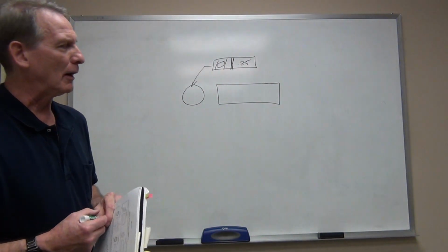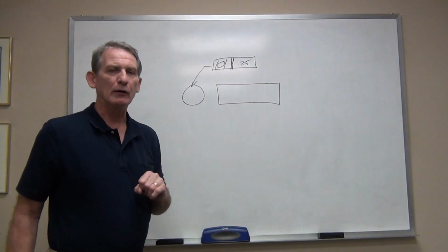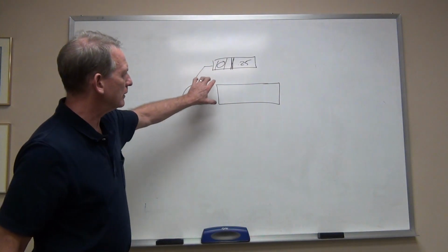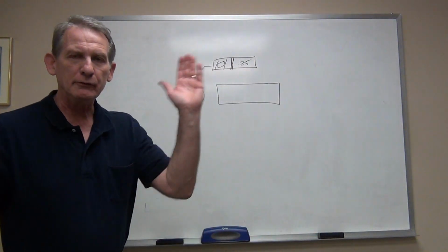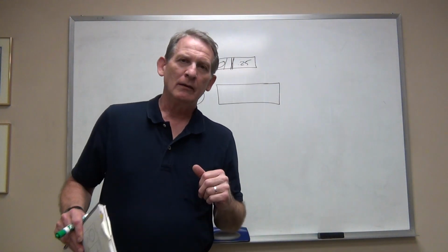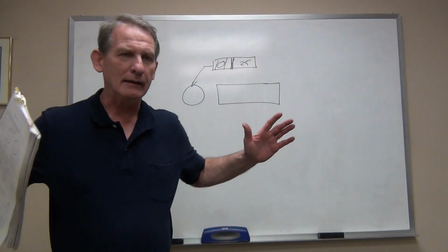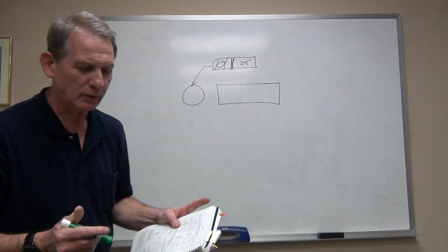And so let's think about how we are going to put a boundary around this shaft in its entirety. Now with circularity, we're looking at a whole bunch of individual slices. With cylindricity, it is basically integrating all of those individual slices into a single tolerance zone.